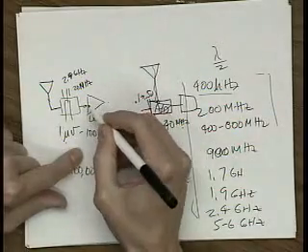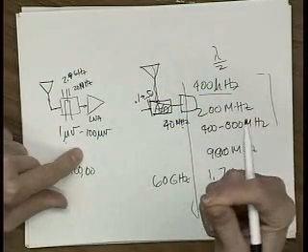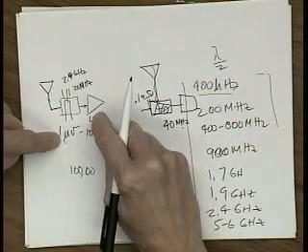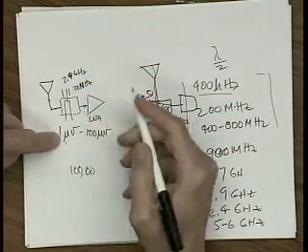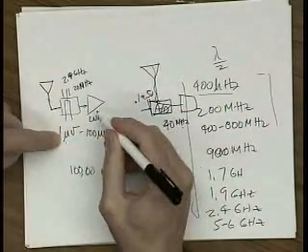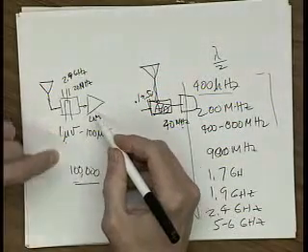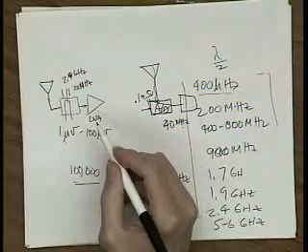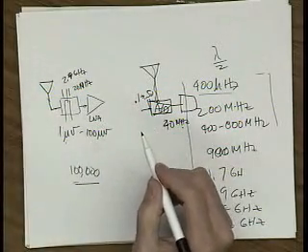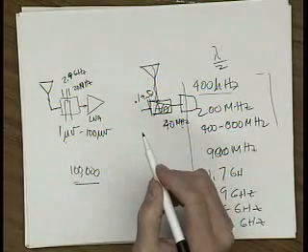The problem is every transistor creates noise. You don't want the noise created by your circuit to be bigger than the noise of your signal. So this low noise amplifier design is basically trying to make an amplifier that does a lot of gain, while adding the least amount of noise possible. The way you can model the noise is a little noise source in front of every gate. It just adds into the signal.